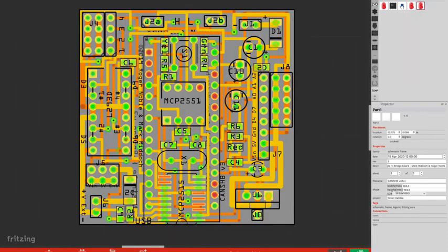The PCB looks like that, and now you can see it is getting a lot more crowded. You will note that I've used on my power lines, where possible, a wider track than standard, particularly as we're driving external components that may take more significant power than the standard ICs. You can do this for any track.